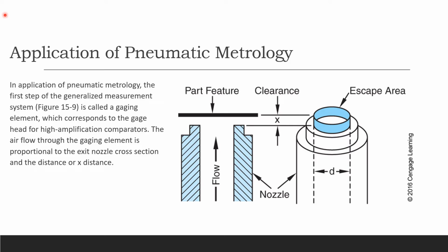When you think about the pneumatic metrology features, they recommend air gauging for small holes, highly polished parts, fragile or easily deformed parts, remote measurements, and the inspection of multiple part features. So those are what we can do with this instrument. That's based primarily on the rate of flow type, the one that I showed you in a previous slide, of air gauge with flow meter columns, but many of the features apply to other air gauges as well.